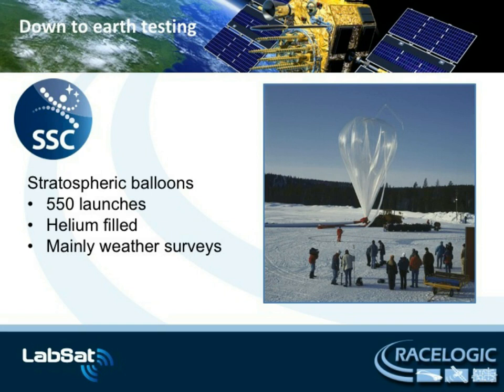SSC use GPS and GLONASS in a dual configuration to track the progress of their balloons, so they require an unrestricted receiver to continue operation when it goes beyond 18 kilometers in height. GNSS conditions are quite straightforward for the balloon due to the low dynamics involved, so this is the only test they required to validate their systems on a balloon.